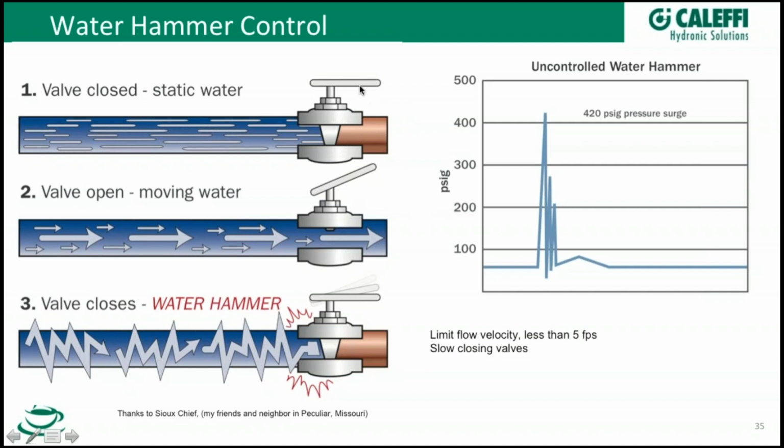And by the way, you can even do that manually shutting the ball valve. In fact, where you'll see this happen sometimes is when the firemen are running a fire hydrant out on the street, and they put the wrench on it and they crank it down quickly, and everybody on the street has a relief valve pop on their water heater because they just set up a big shock wave in that main, which then goes right into your house and can pop the relief valve on your water heater, on your fire sprinkler, something like that. So we want to be able to address this.